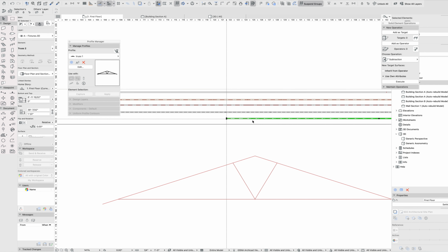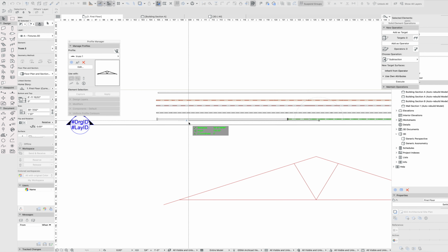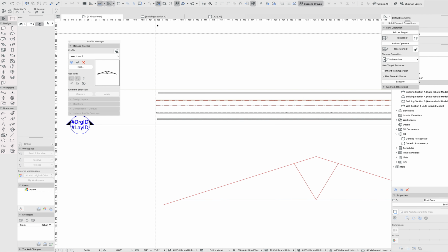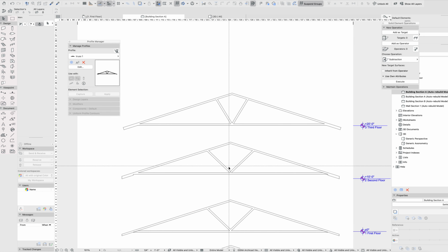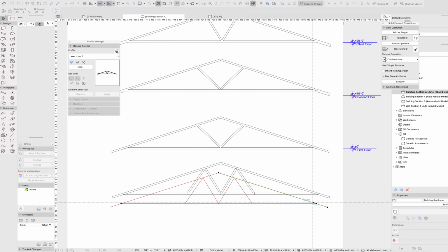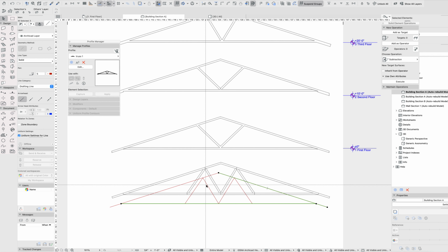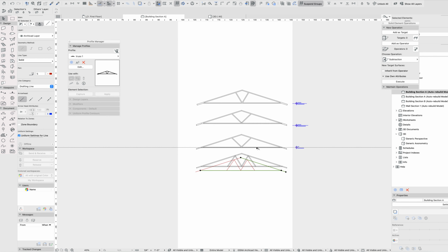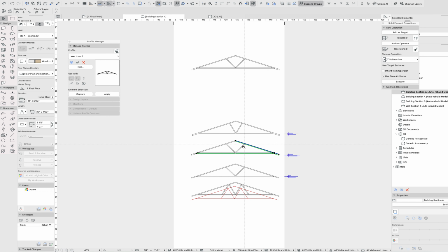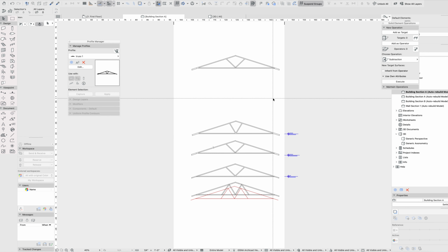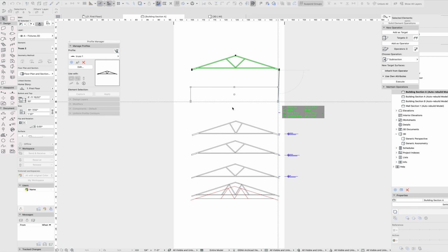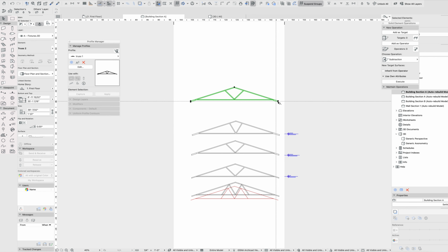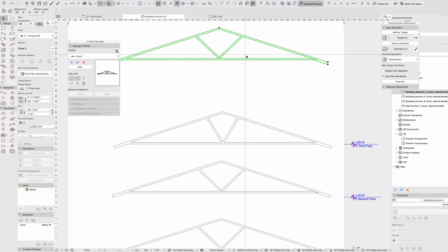Unlike the truss editor, I don't have the option to go back and retain these pieces or pull these pieces out of the truss that was saved. So you would have to create and essentially retain the beams on a hidden layer if you ever needed to go back through and edit it. But this is a great option. It's a perfectly viable option for dropping in trusses, especially if you're just tracing out shop drawings.